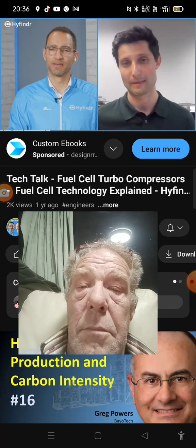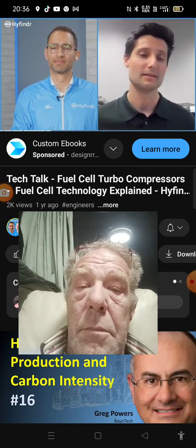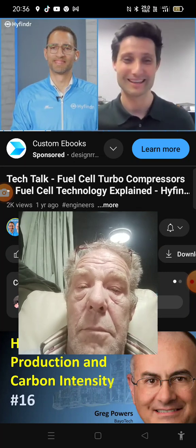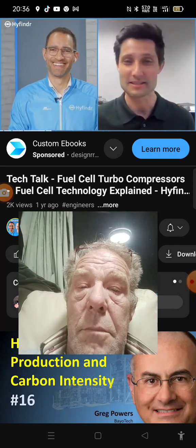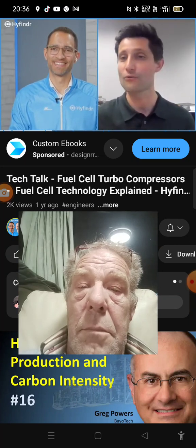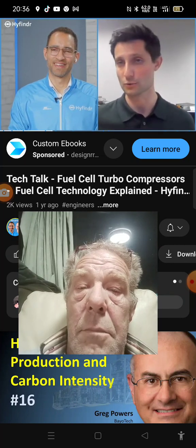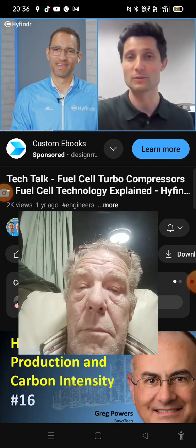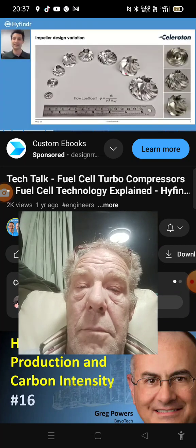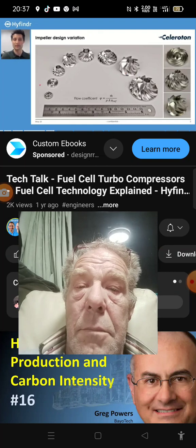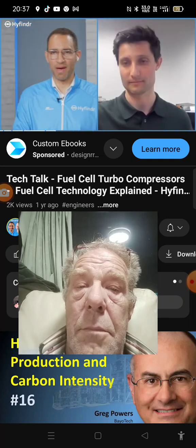What's the main difference? So the main difference is directed, it's a very technical question actually. The difference is directed to the flow coefficients. So essentially the throughput that such a compressor needs to be designed for. For instance, once we go towards axial flow designs, which is a classic for gas turbine designs, we have high mass flow requirements. Whereas when we go to really radial designs, which is, for instance, a purely radial design, 2D even, we have very low mass flows. All right. Okay. So the mass flow essentially makes a difference.